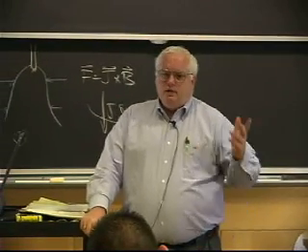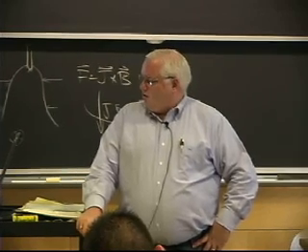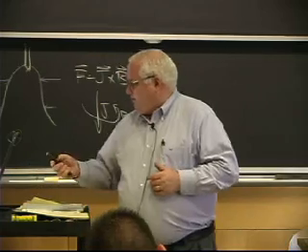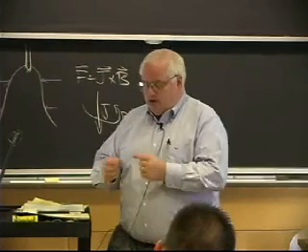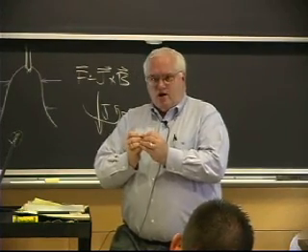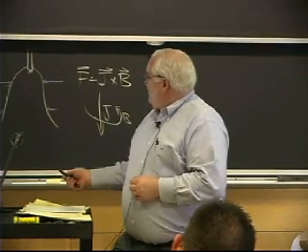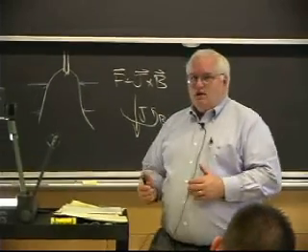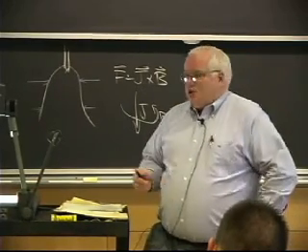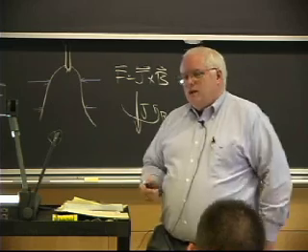discovered back in the 1800s, kind of the mid-1800s, if I remember. And it turns out we now understand that it's not a true phenomenon at all. That's not the physics of it. They actually thought that somehow the high voltage was causing the air to ionize, just a straight DC voltage when you brought things close together. But that's not, it takes thousands of volts, and even though the welding handbook describes this as one of the ways for arc ignition, it can't be because I don't have thousands of volts in a welding power supply, okay?